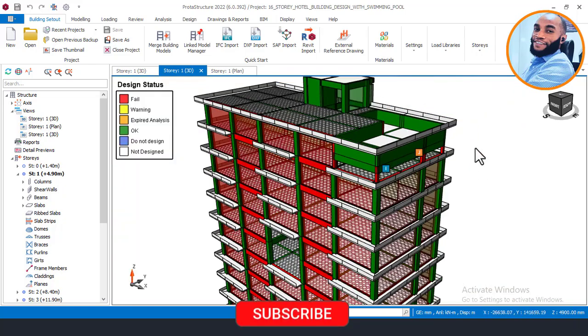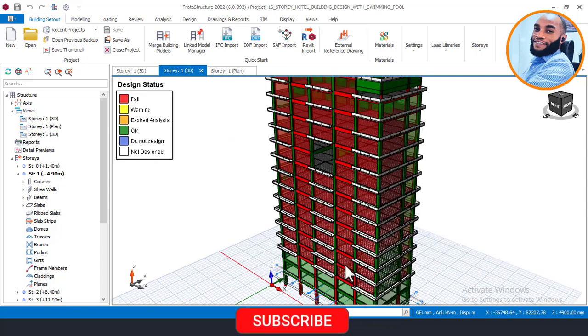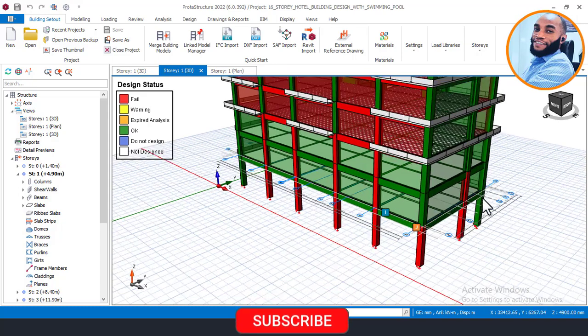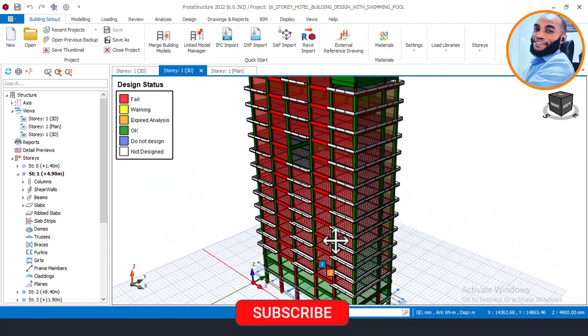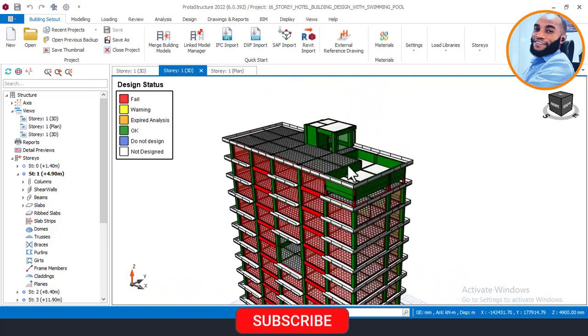And to do that, I'll begin directly from story 1, to see the reason why most of the columns here on story 1 and also the beams are failing. Now, even if some of your members are showing green, which is okay, I still advise that you check each of the members to see the kind of reinforcement that the software used to design for that member.